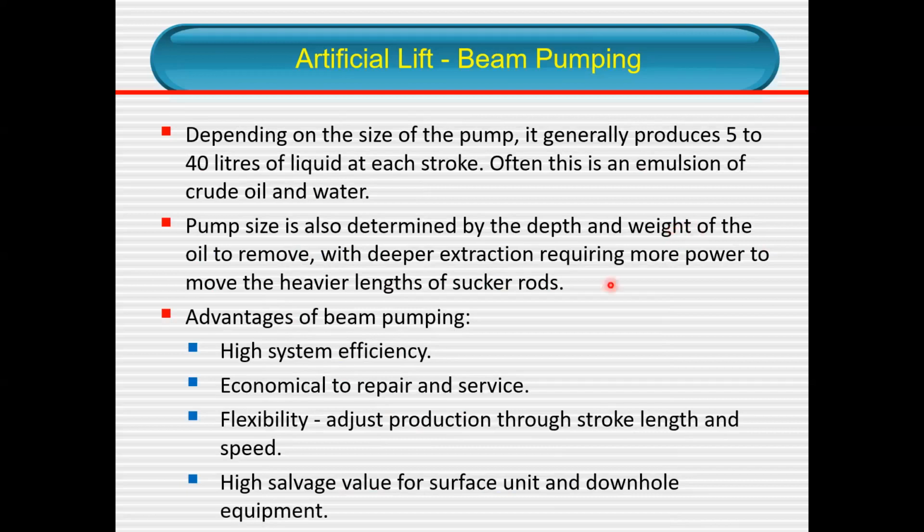Advantages of beam pumping: high system efficiency. Of course, onshore, it works very well, cheaper, economical to repair and service. Flexibility, adjust production through stroke length and speed. You can know how much to produce per day based on the limit that you have put. High salvage value for surface unit and downhole equipment. Once used, you can always reuse it in another well.